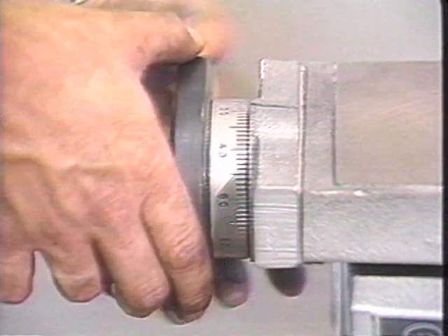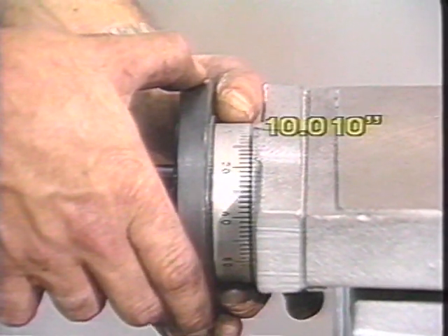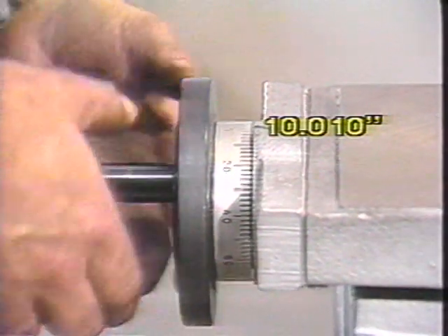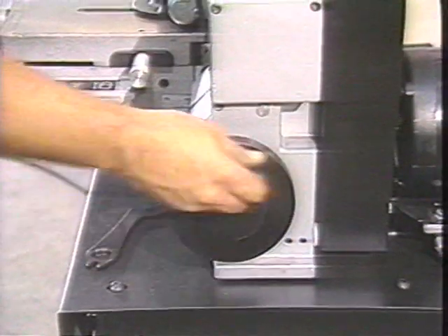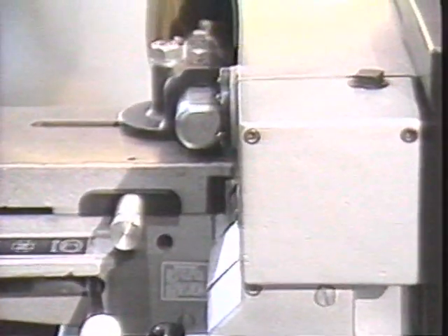Turn on the lathe. Carefully turn the cross slide crank until the cutter tip slightly touches the drum face. Hold the cross slide crank with one hand and turn the micrometer dial with the other hand. Set the dial to reflect the same reading that you obtained with the drum micrometer. Rotate the cross-slide crank so the cutter tip is moved away from the face of the drum. Move the carriage traverse crank so the cutter tip is over the deepest groove in the drum.